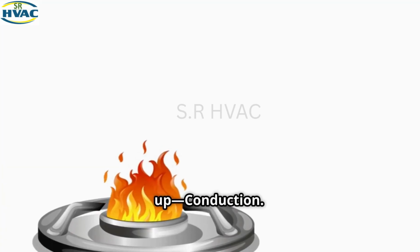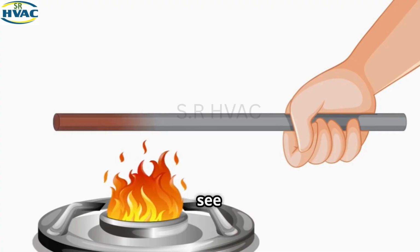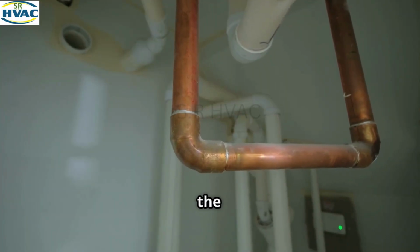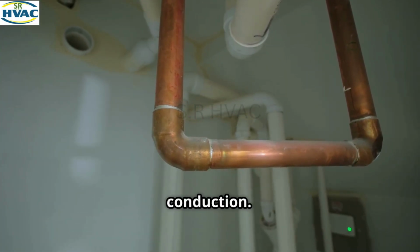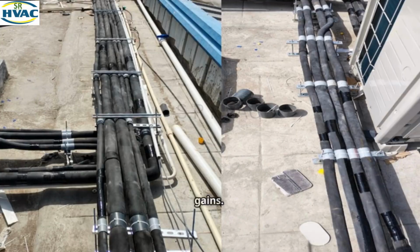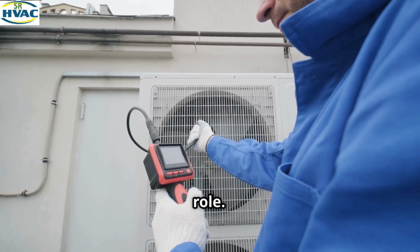Conduction. First up, conduction. This is heat transfer through solid materials from molecule to molecule. You see this in refrigerant lines, compressor components, and even in ductwork that's not insulated. Example, when a hot copper pipe from the condenser comes into contact with a bracket, heat will transfer to that bracket. That's conduction. Why it matters in HVAC? Insulating refrigerant lines is vital to reduce unwanted conduction losses or gains. And when diagnosing overheating components, conduction plays a big role.